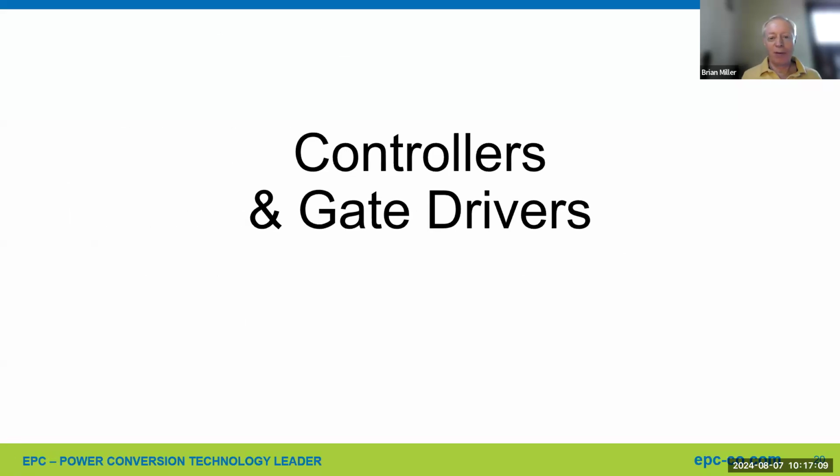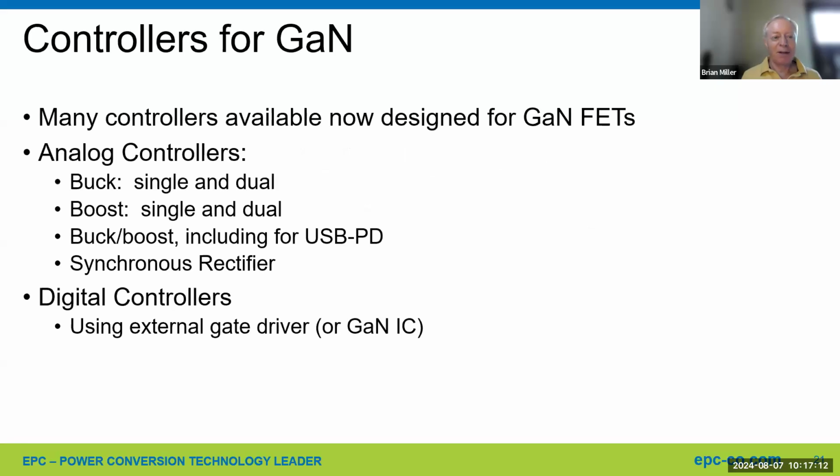Now let's go on to controllers and gate drivers. So controllers for GaN: versus a few years ago, now there are many controllers on the market that are designed for GaN FETs. Of course, two different categories. First is analog controllers. And the range there is buck converters, both single and dual. Boost, both single and dual. A buck-boost, including another one for USB power delivery. And there are also synchronous rectifier controllers that can be used for GaN FETs.